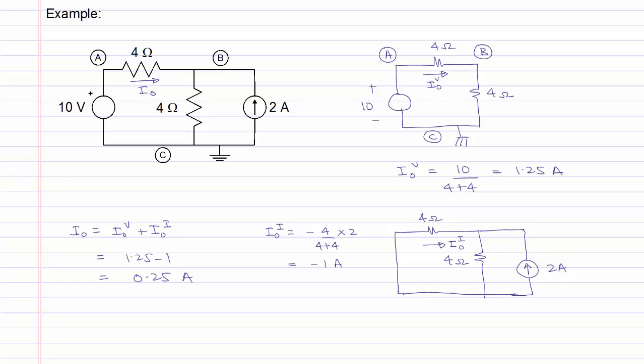To summarize, when we switch on the voltage source, then all the currents and voltages in the circuit are the response to just the voltage source. And when we switch on only the current source, then all the voltages and currents are the responses to that current source. And if we switch on both the current and the voltage sources, we combine the partial results and we get the overall response, which will be the sum of the individual responses.